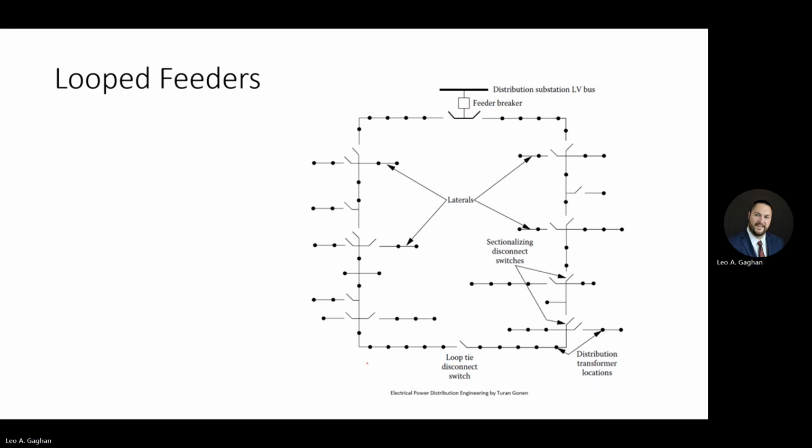In the normally open situation, we're going to feed current all the way to that tap, but that's normally open. If you close it, you could feed both. What ends up happening is if this is normally closed, fault detection might get just a little bit more challenging. Well, with a single feeder, I guess it wouldn't, but double feeder it would.